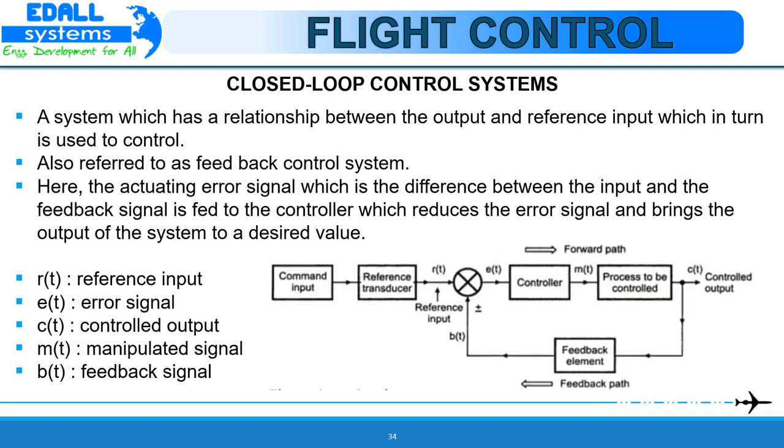The main advantage of a closed loop system is that the accuracy of such a system is very high because the controller modifies and manipulates the actuating signal. Such a system senses the environmental changes as well as internal disturbances and accordingly modifies the error. In such a system, there is a reduced effect of non-linearities. The bandwidth, or operating frequency zone, for such a system is very high.